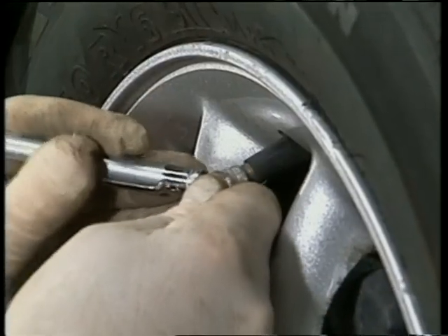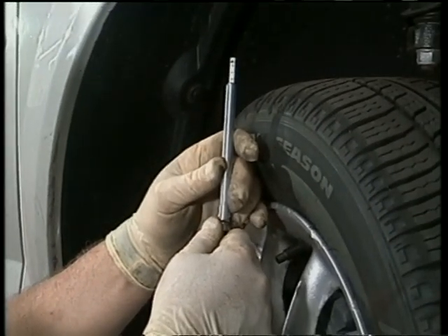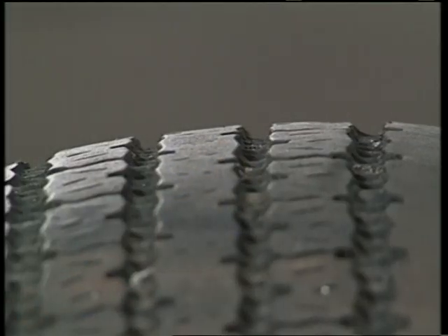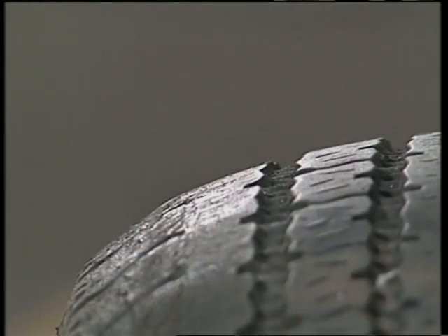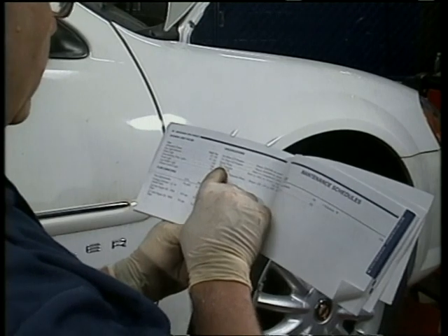Many modern tires are meant to roll only in one direction and have left and right sides. Air pressure is also critical. Tires that are not inflated to the correct pressures will cause steering and handling problems, as well as accelerated or even uneven tire wear. Check the owner's manual for proper tire pressure or look inside the door frame on the driver's door. And there you have it, the basics of vehicle alignment.